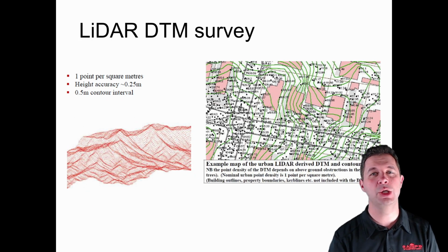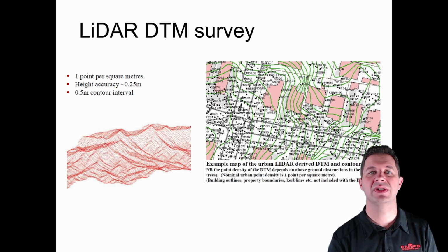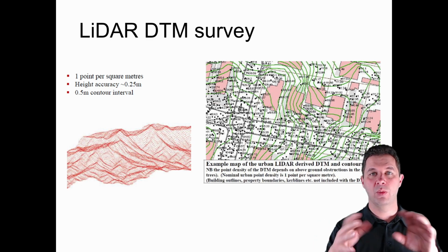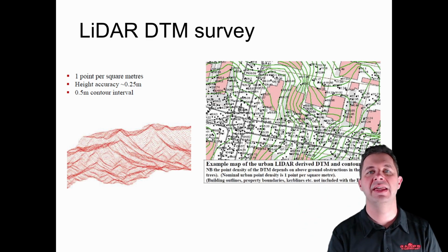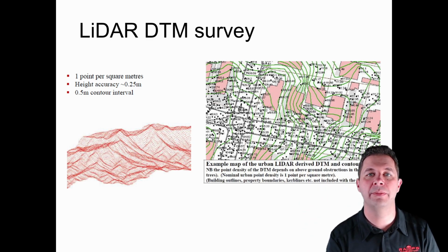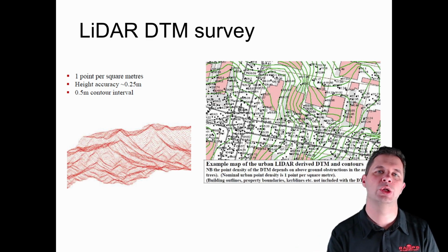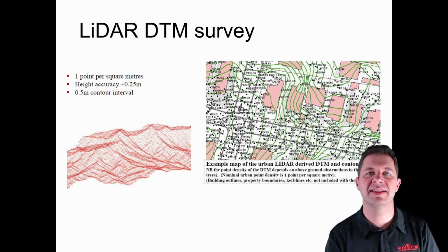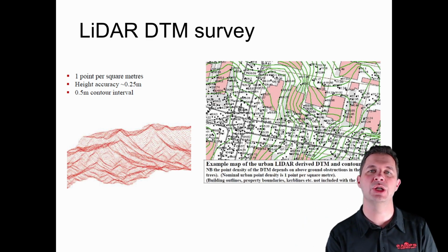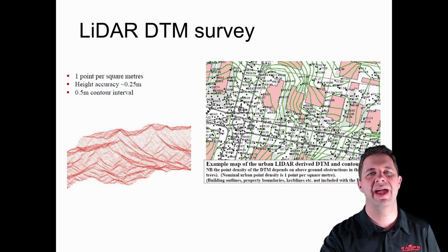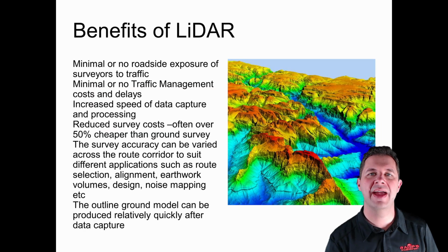We can also create digital terrain models, or DTMs, with something like LiDAR, where we're looking at the distance when we're taking our survey, an aerial survey, either from satellites or from a plane or from a drone or something like that. This allows us to survey an area and look at it topologically, of how it changes and what discontinuities we might have.